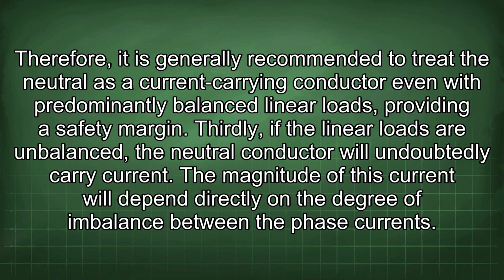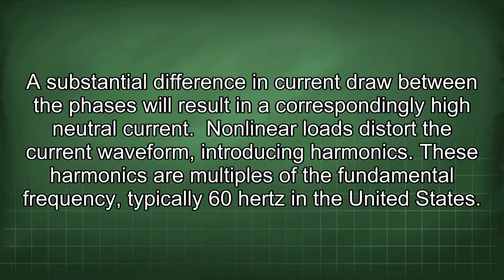Thirdly, if the linear loads are unbalanced, the neutral conductor will undoubtedly carry current. The magnitude of this current will depend directly on the degree of imbalance between the phase currents. A substantial difference in current draw between the phases will result in a correspondingly high neutral current.